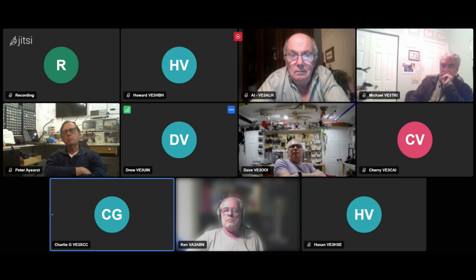And as soon as you bump it up a level, now suddenly you can see, oh, okay, my 10 dB of noise is now 10.5, so I've got a 0.5 dB contribution from my circuit, as opposed to trying to measure 0.5, which is within the quantizing error of your digital system. You can't really measure anything there. It comes up as zero, right?